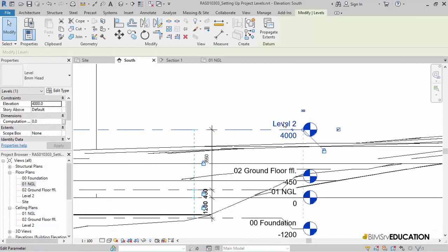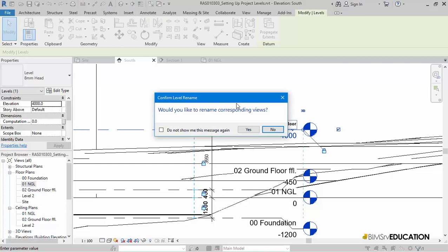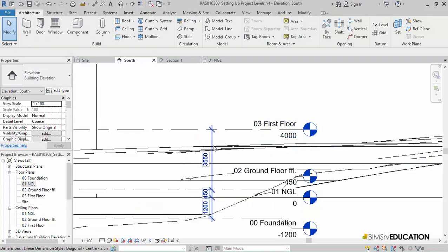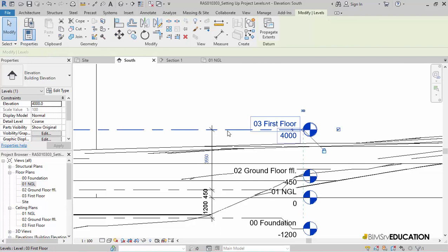I now need to change the distance between ground floor and first floor. I want this level difference to be equal or in multiples of my staircase riser. This way I prevent fractional dimensions in my riser height. In my staircase I am using the riser of 178, and this will result in 18 risers between ground and first.